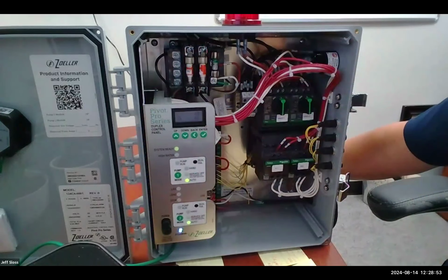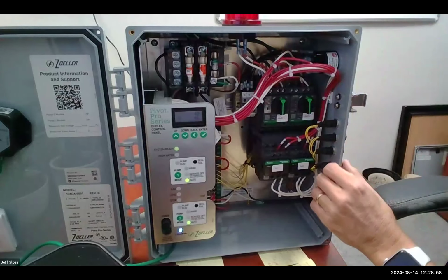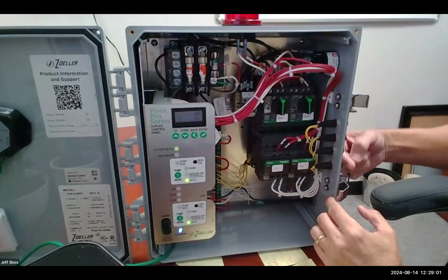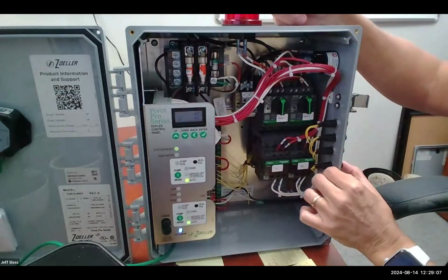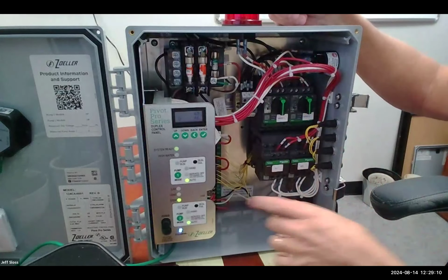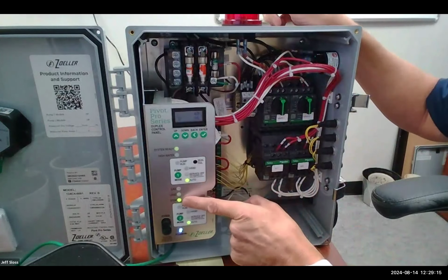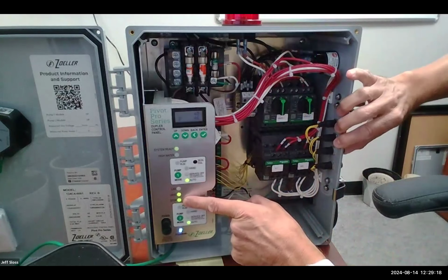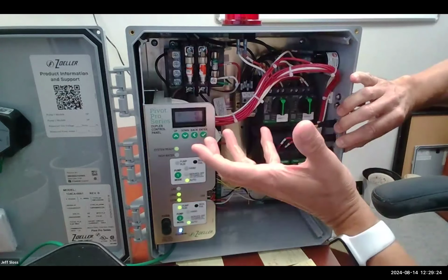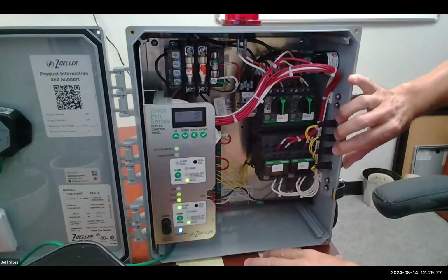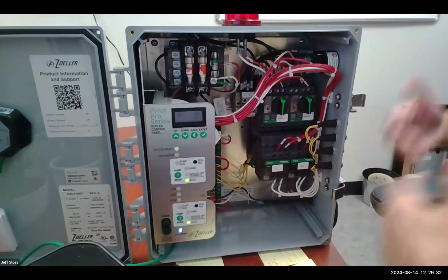All right. So what do I mean by float faults? These little buttons over here are representing my floats. So normally these 4 represent the 4 floats that are down in the tank. If I turn my stop float on, that's the lowest float. You can see this LED turned on. Is that in my screen? Okay. Yeah. So the stop LED turned on, and then my lead float came up, and I don't know if you could hear that, but the contactor pulled in. So now the pump is running. Now the water goes down. So the lead float turns off, the stop float turns off, the pump turns off. Real simple. Next time I do it, it'll go to the other pump.